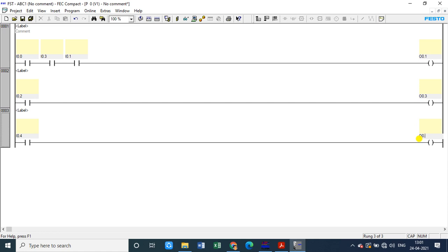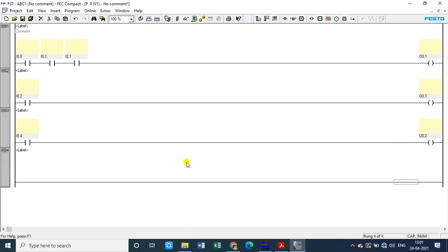That is for getting A minus. A minus means the 1M2 coil. 1M2 coil is connected to port number 2. Okay, yes: 1M1, 1M2, 2M1, 2M2. Okay, so click on this. Then next rung after.